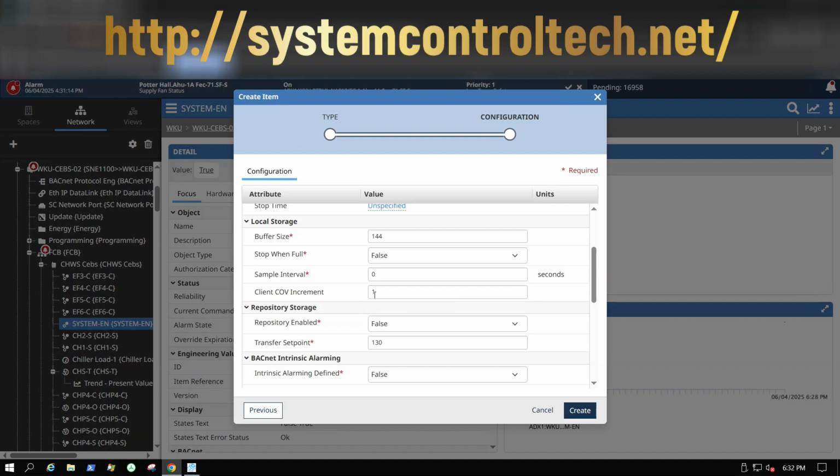That's what happens here. Now, how can you use this? Another way you can use this, if I had this on an analog point, which we'll get to here in a moment, I can actually set this to where it's only going to capture every however many seconds, 600 seconds or whatever, at a change of, if it's the temperature, it can be 10 degrees. I could set that at whatever I needed it to be as well, but we'll get more into that here in a bit.